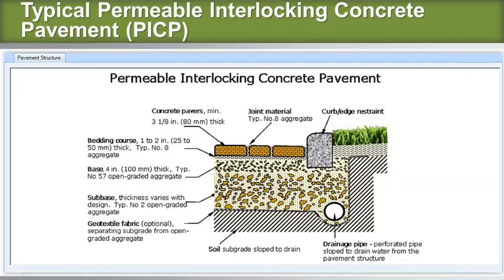So I'm going to spend the next hour or so talking about permeable interlocking concrete pavements, and particularly the Permeable Design Pro software. For those of you who may not be familiar with permeable pavements, this is basically what they look like. We take an existing pavement that has typically got dense graded aggregates, and we change it so we allow, instead of water to run off the pavement, water to permeate into the pavement surface itself.